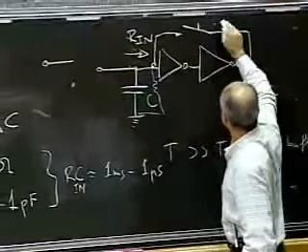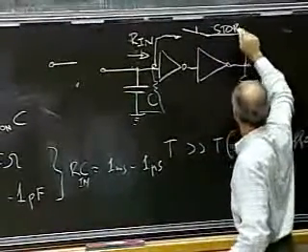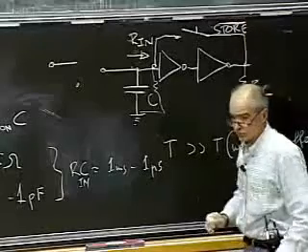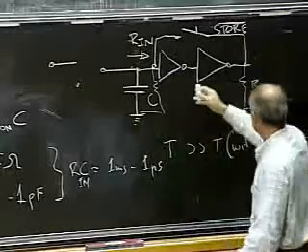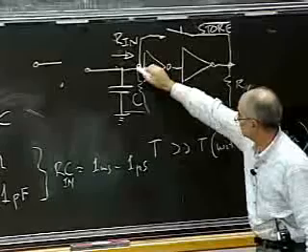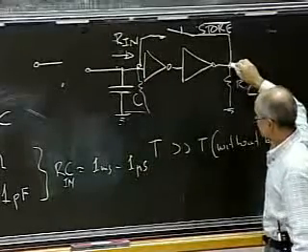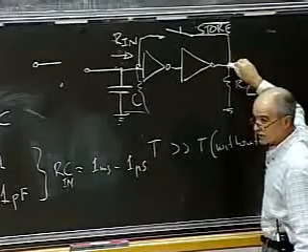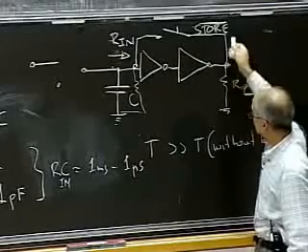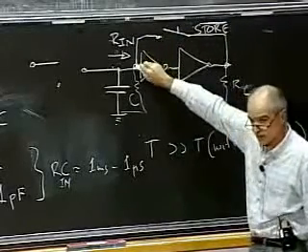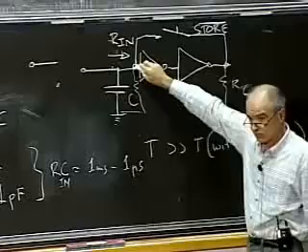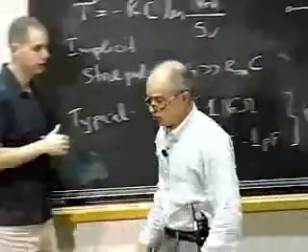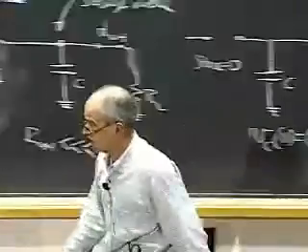So this basically is the complement of store. So what I'm doing now is I put a charge here. It produces a valid 1 at this point, and then I'm feeding this valid 1 back to the input. As you can see, this will now allow me, even though I have a high resistance, to store the value for a long time.